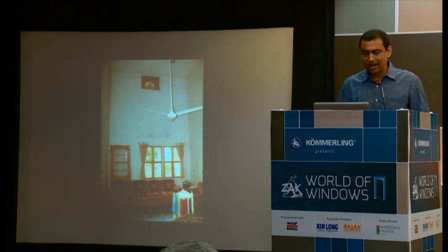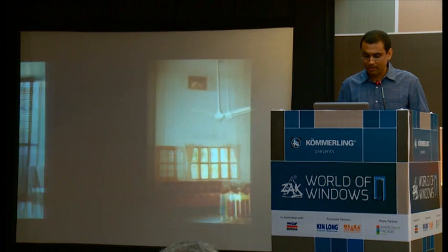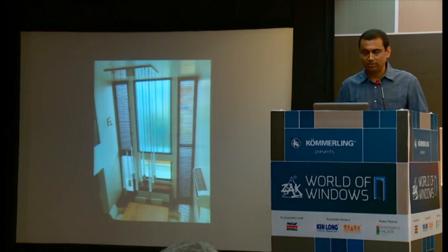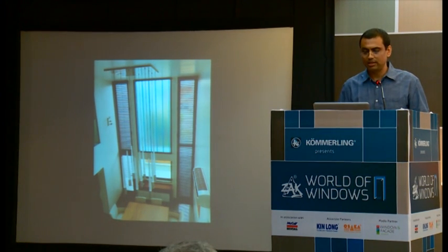This was a dining area earlier, and this is what we have designed. There are three different elements in this image. You can see that there are louvers at the sides, which are motorized louvers. There is a fixed glass on the top, which is channel glass, which brings natural light. And there is a window at the bottom, which gives you the view. So these three functions we have separated, and each element is giving a separate function.